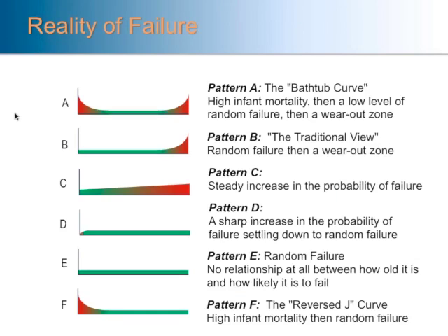In reality, things fall into one of these 6 failure pattern categories. These were derived and developed in that study that was performed by commercial aviation that resulted in the reliability-centered maintenance tactic or method or methodology. And interestingly, for an aircraft, these were the actual percentages of equipment failure associated with the components.